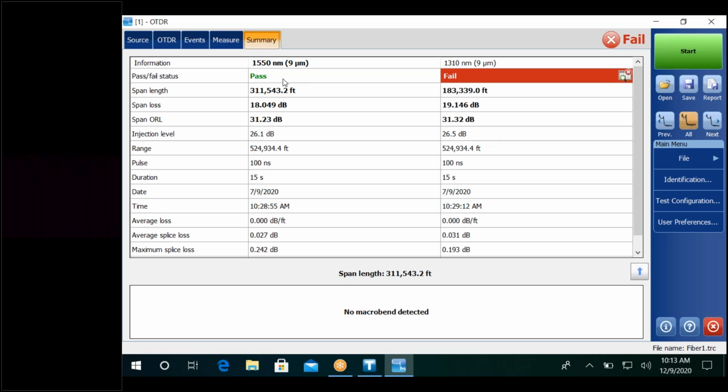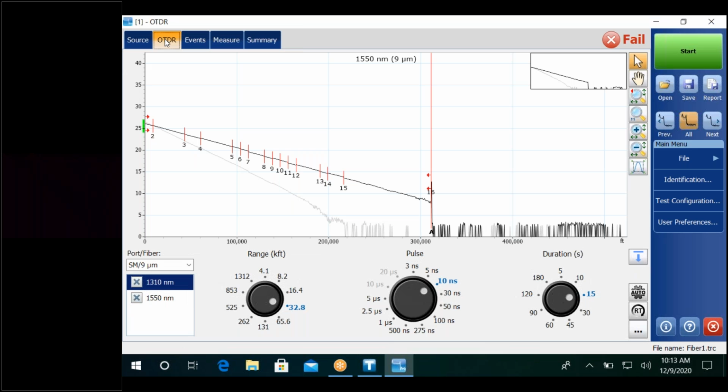Again, most people that have operated an OTDR for a long time can see what the graph is looking at. I've been in the field with guys that say, oh yeah, we've got a really bad splice right there at number 7. And you're like, what? How can you see that? Their eyes are so trained. You can always go in and zoom into an event, really blow it up and see that stuff.